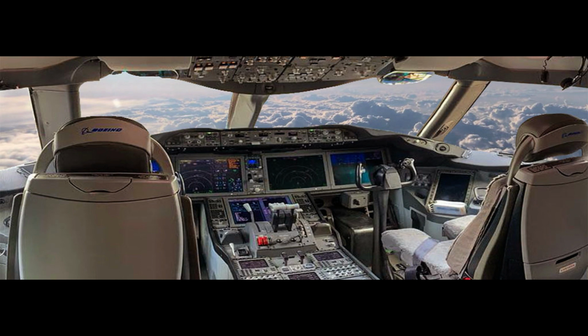For higher safety standards, commercial operators must observe restrictions in Title 14 of the Code of Federal Regulations, 14 CFR, Sections 121.579, 125.328, and 135.93, according to their regulatory classification. Adoption of these limits by private operators would add a safety margin to flights conducted under 14 CFR Part 91 regulations in many cases.